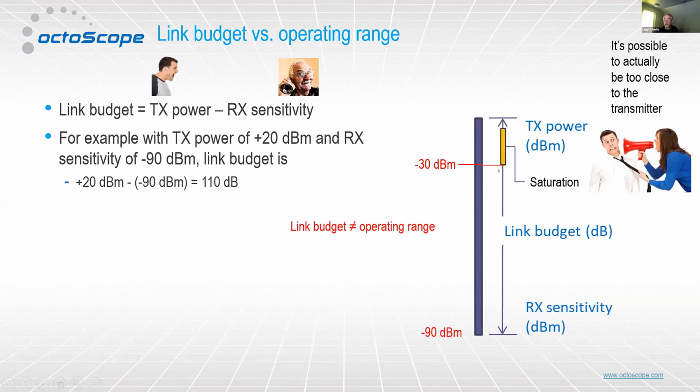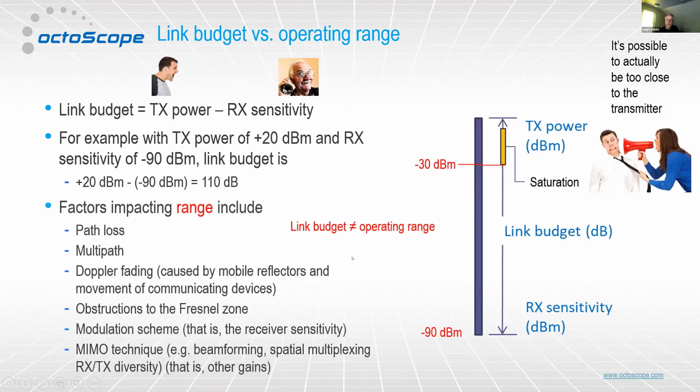So there's what's known as an operating region between the highest level signal that a receiver is built to handle and the lowest one. And in Wi-Fi, the range is something like this: negative 30 dBm at the top side, down to in the neighborhood of negative 90 dBm at the bottom side.